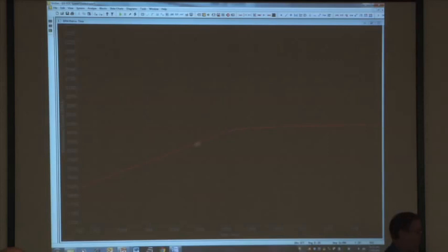Right. It's constant torque. But then finally, as it starts getting close enough, the speed regulator says, back off. I'm actually using dynamic integrator clamping here so that it doesn't overshoot. And so it starts backing off. It brings the current level down to bring it into a nice, smooth 2,000 RPM.